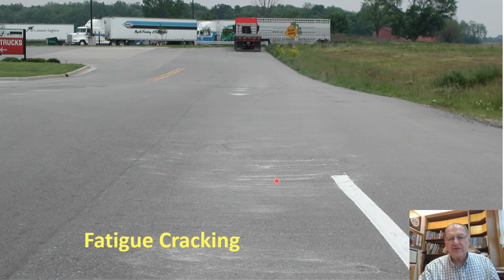And not only is it fatigue cracked, but you can see mud that is pumping up through it. Well, it turned out that this was a brand new site for this truck stop. And what was not recognized at the time of construction was that there was groundwater in this area. And so what's happening is the subgrade became very soft, and as a result, we had very high deflections, and